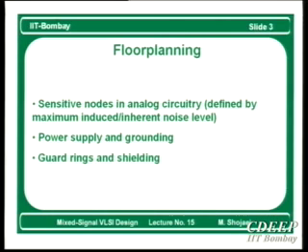So what affects the floor planning when we are talking about a mixed signal circuit? We have to be worried about analog signals which are sensitive. What do we mean by sensitive analog signals? Suppose you have an analog signal which has a very small amplitude. Therefore, it's a sensitive signal, and any node associated with that signal is a sensitive node. Or, for example, you have a high impedance node. That is a sensitive node because it can easily couple to any noise source in the circuit. So these are sensitive nodes or signals that we have to take care of.